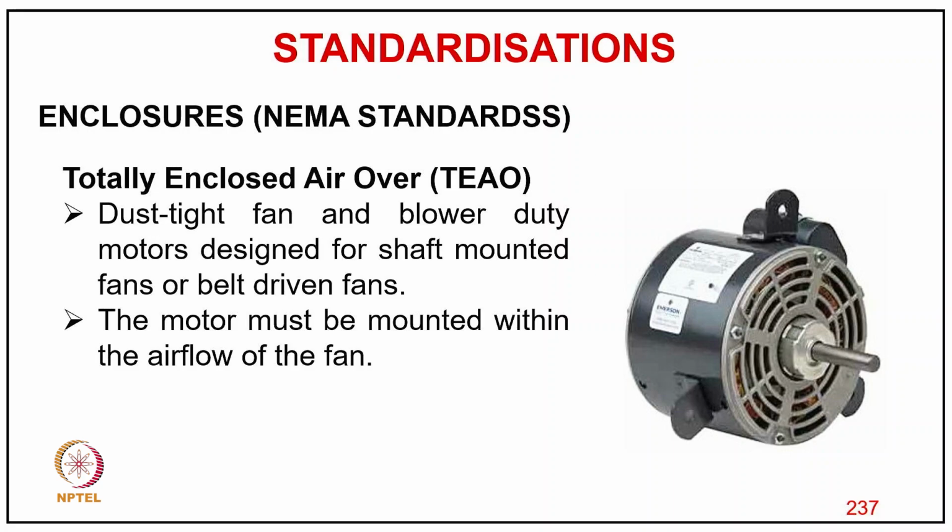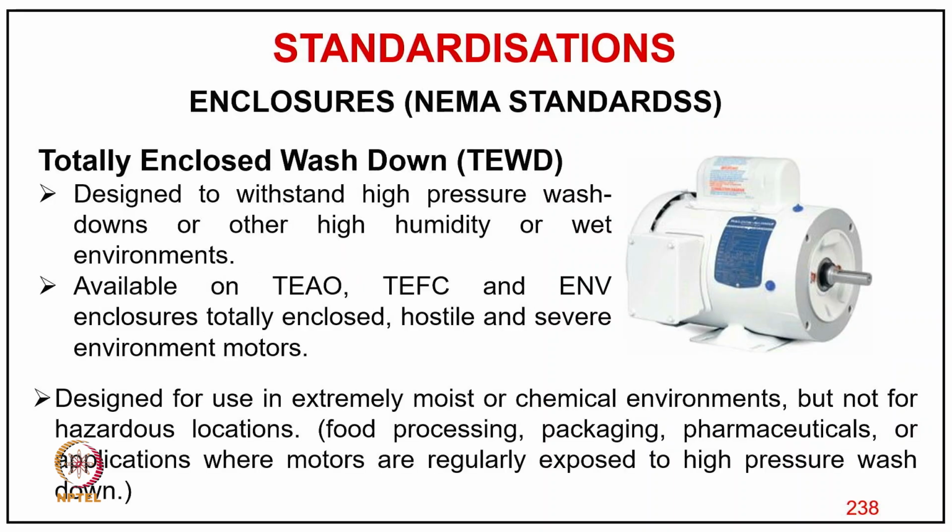Totally enclosed air cooled. Typically you can see how the motor looks. So these are dust tight fan and blower duty motors designed for shaft mounted fans and belt driven fans, and the motor must be mounted within the airflow of the fan.